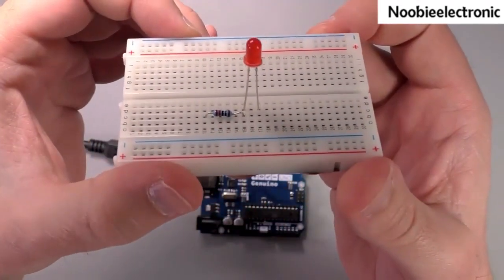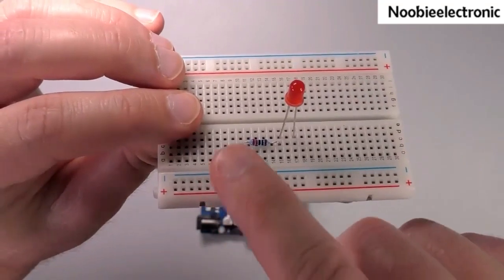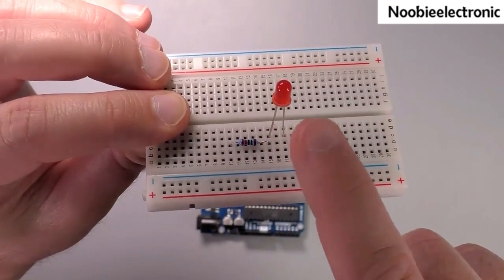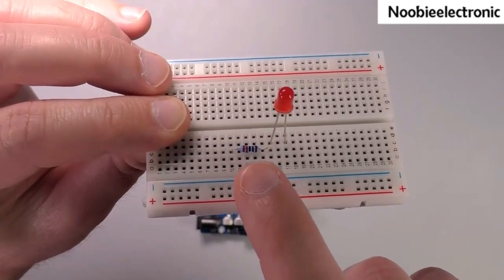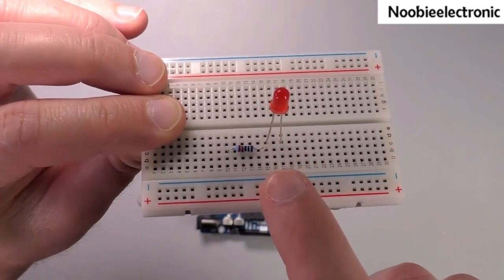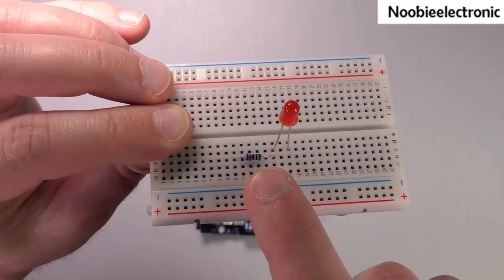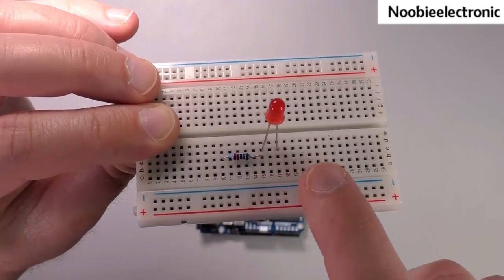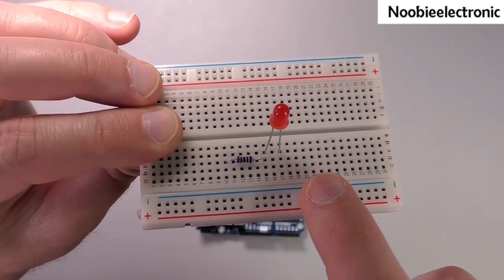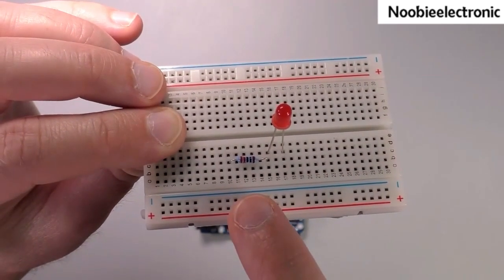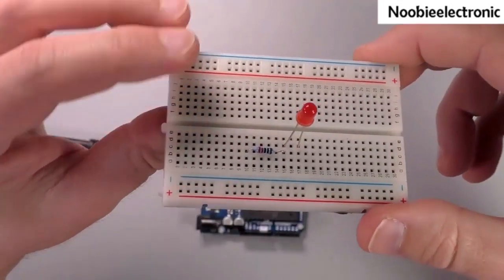There you go. Either one way or the other is fine, because the current that will eventually flow through both devices doesn't really care whether it goes through the LED first and then the resistor or vice versa. The amount of current that flows through both devices together will limit itself depending on the total resistance in the circuit which contains the LED and the resistor together. So whether the resistor is before the LED or after doesn't matter. I typically connect it on the anode just because it's easier for me to remember then where the anode is.